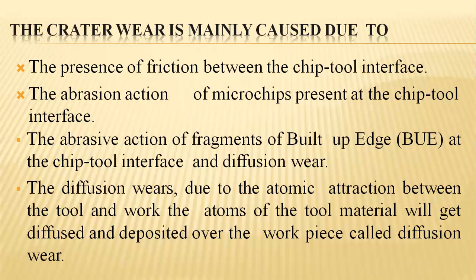And even the diffusion wear occurs due to the atomic attraction between the tool and the work part atoms or the tool material. Normally, it will be getting diffused and deposited over the workpiece, which is generally called diffusion wear. Due to this agitation also, crater wear will be getting produced.